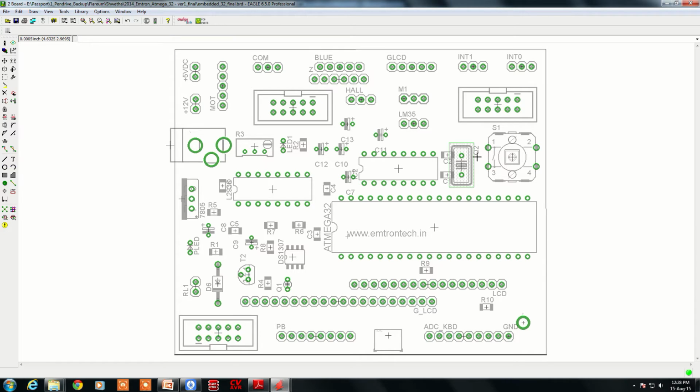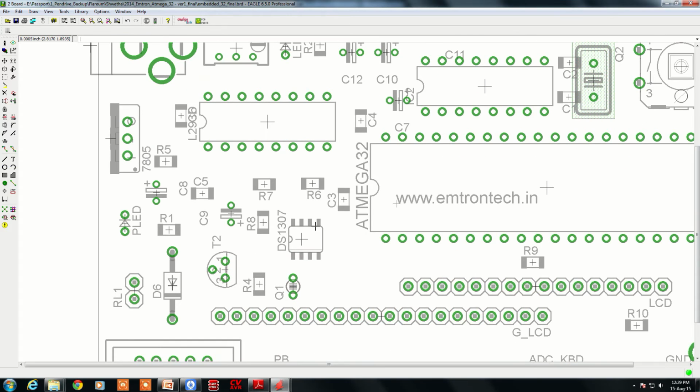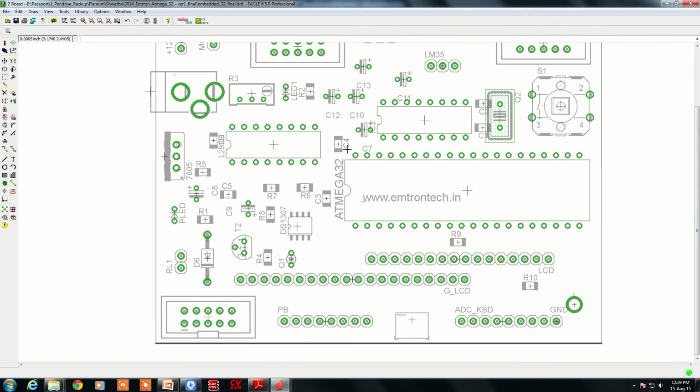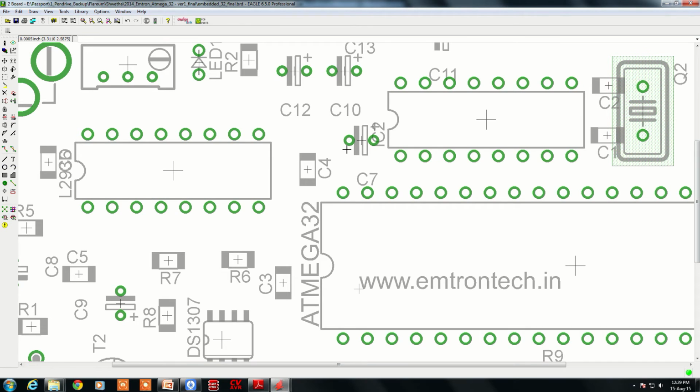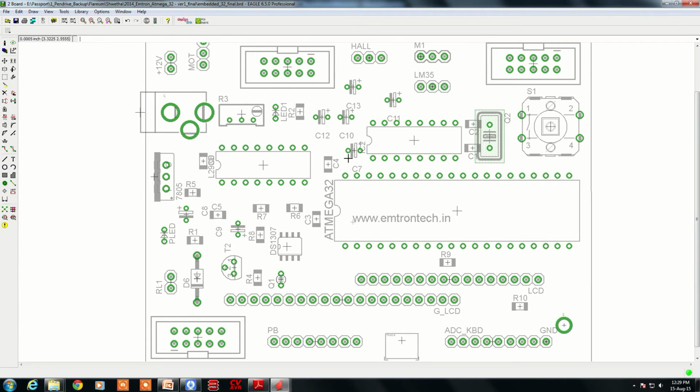The board is operating on 8 megahertz right now. You can go up to 16 megahertz by using this crystal. The reset switch is mounted here. A real-time clock RTC DS1307, which is an SMD IC, is mounted here. All the resistors and capacitors are surface mounted devices. The package is 1206. The capacitors have a direction, for capacitors more than 1 microfarad. On the positive side the symbol plus is printed, and this is minus. Every capacitor above 1 microfarad has a direction.